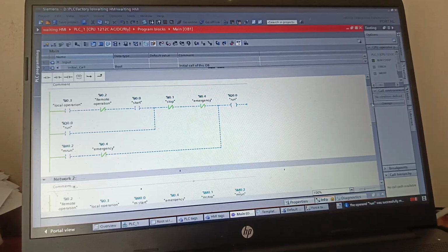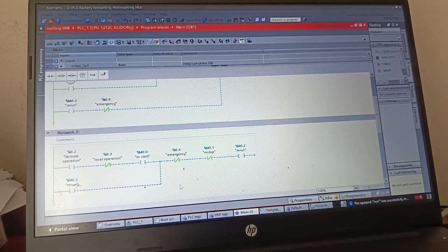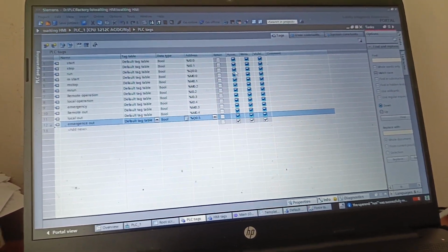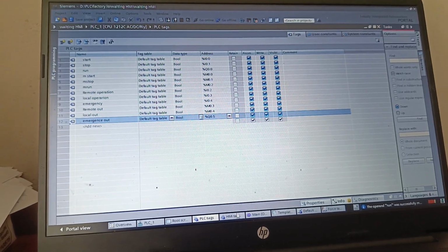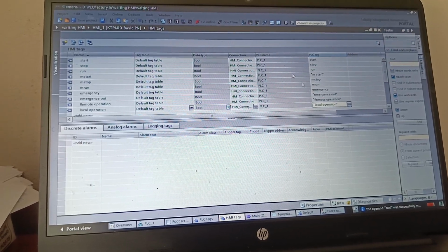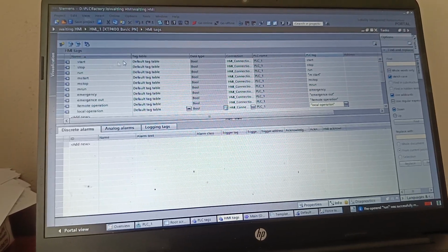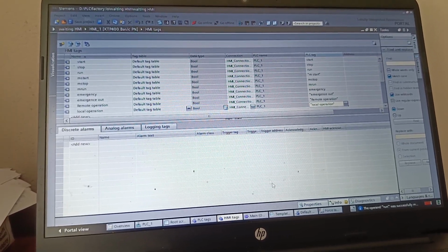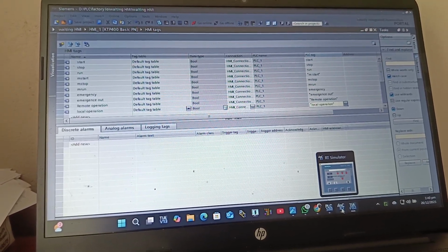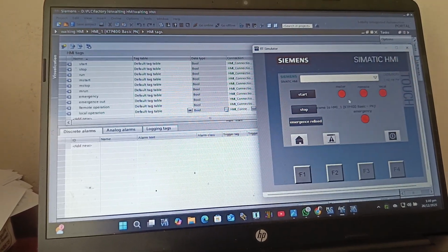The other thing when programming this kind of HMI and PLC tags, you have to map them. Like I said, you can't map from the PLC side tags. You have to map from the HMI tags. So what you're seeing, these are PLC tags which I've mapped together with the HMI tags. HMI tags should be all memories. There's nothing like you need to output something unless you are doing analog, but they should be memory tags that are to trigger something.